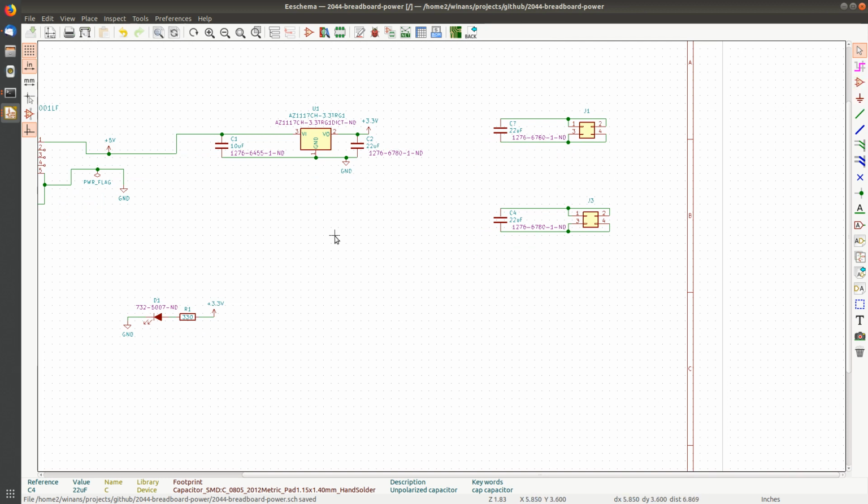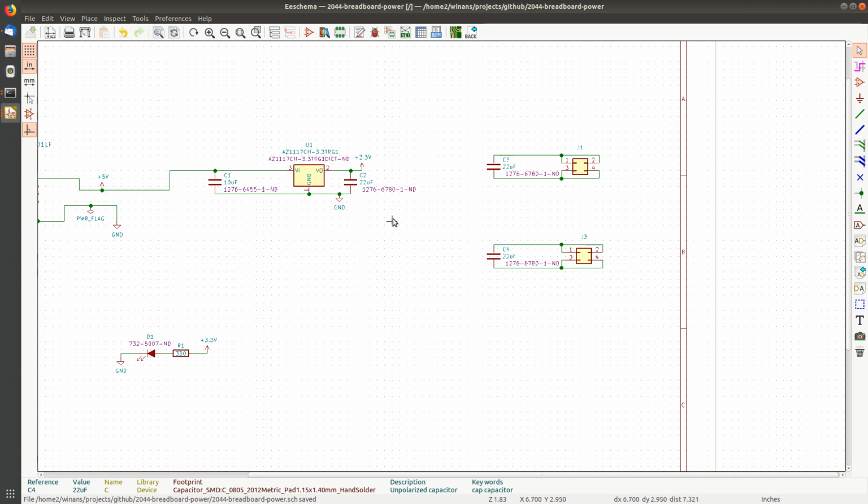Now what I'm going to do is put a net name on here and there. What's a net name? Well, just like when I put a 3.3 volt here and a 3.3 volt there and a ground here and a ground, that named and made these nets meaningful to KiCad. Now I'm going to go ahead and name it. See this guy here with the A over the wire? It says place net label.